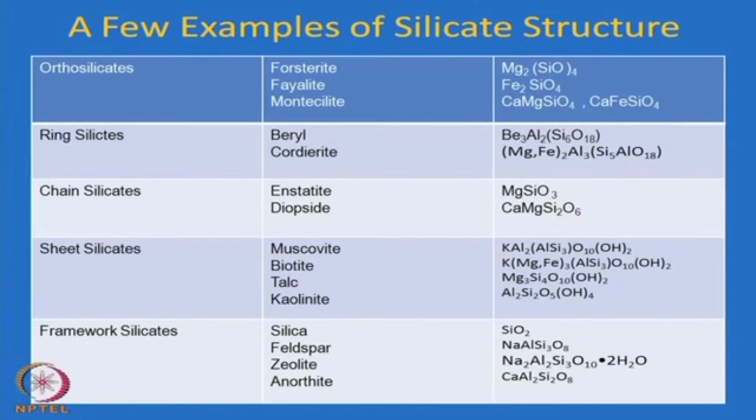Ceramics are mostly used at high temperatures. So, if you are heating a ceramic from room temperature to high temperature, it will always go through some thermal expansion, because all materials have some kind of thermal expansion property. Some of them have a very high thermal expansion coefficient, others may not.